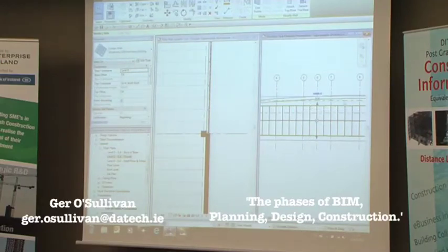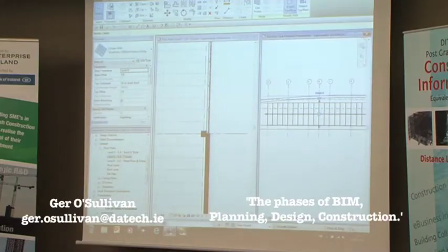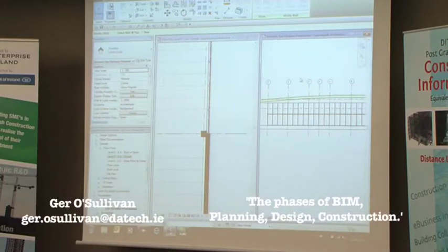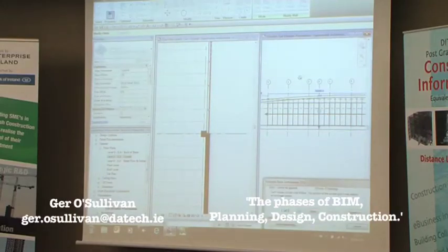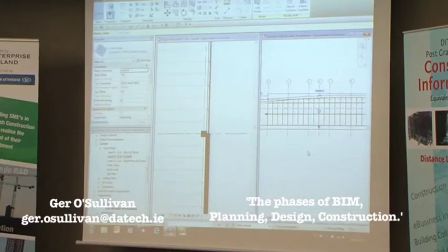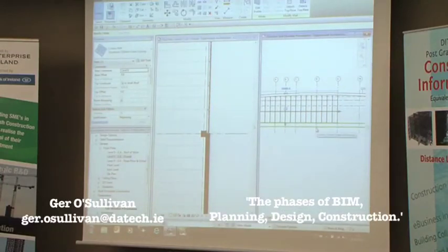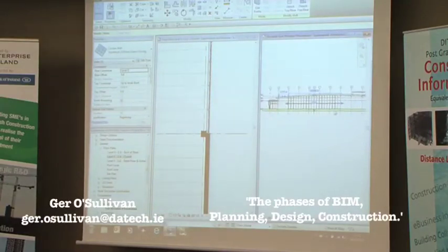We can then select that, and we can attach it to the roof. Maybe we'd like to have a curved top on it. So we'll attach it, and it will attach. And it's even asking me now whether to delete elements, because there are portions there that were only there because of the height. Let's say we'll delete them. They're probably too small to create as a piece of glazing, and the product is telling me that. It's just a soft warning, and I'll say, yeah, delete them, and on we go. Okay, so we've got our elevation. You see the process. We place the information in any view, and it updates every view.